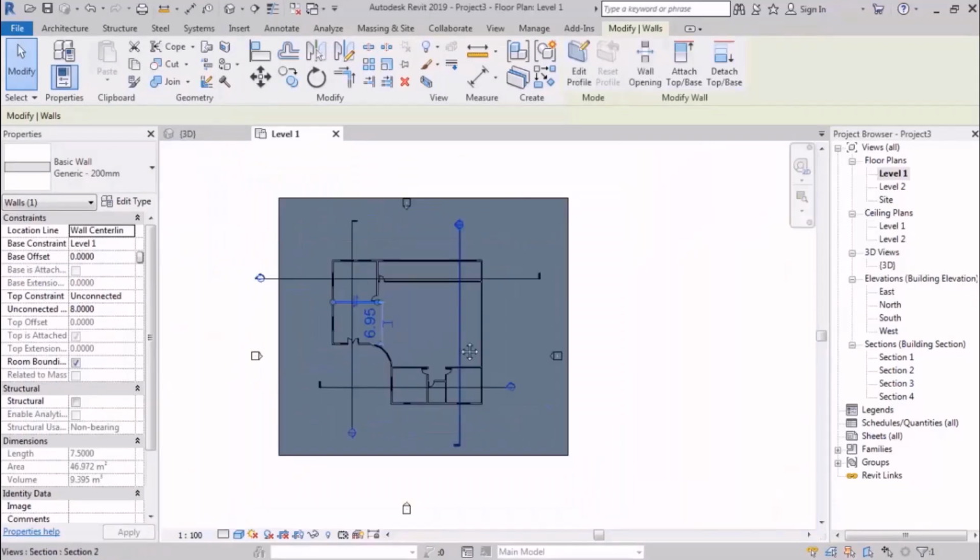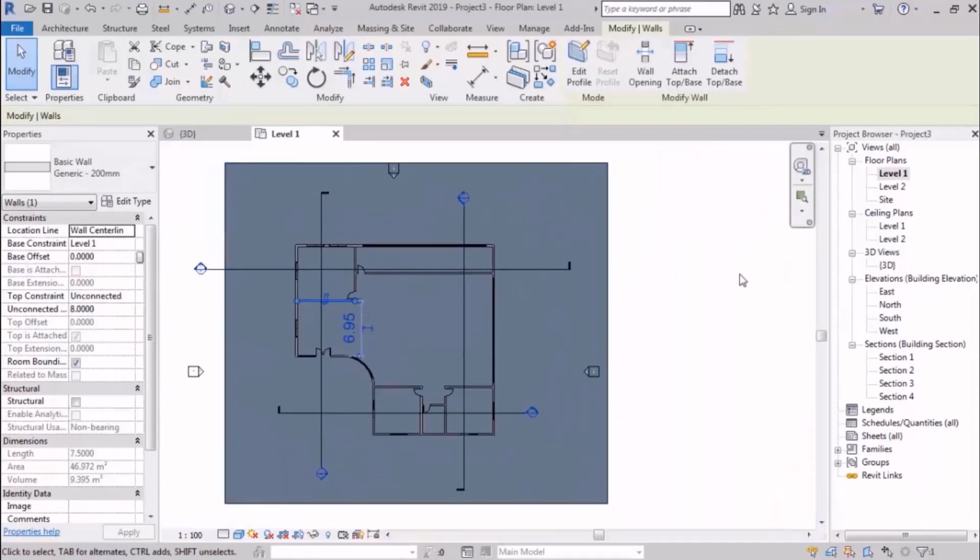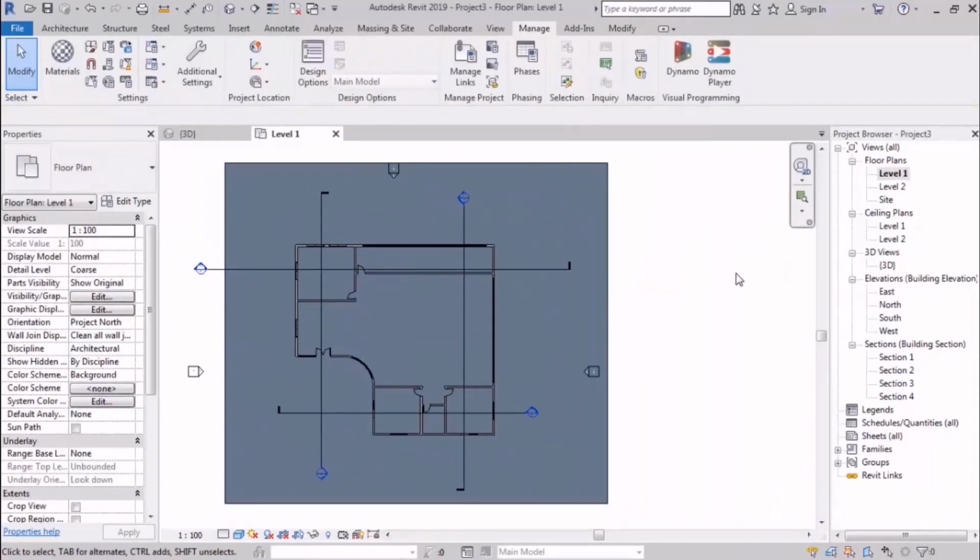And the ultimate point, so that you can go and practice after that, is the management of the shortcuts. In Revit, all the shortcuts include 2 letters, like WT, TW, UN. You can also add a shortcut for those commands that don't have one, or even change the shortcuts if you like.